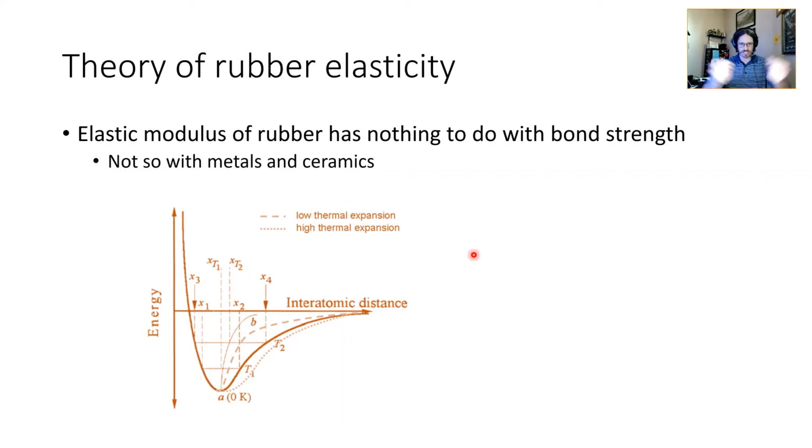It's just those chains elongating that facilitate the stretching of the rubber band, basically. And they have light cross links as compared to a thermoset, so a little bit different behavior. Again, theory of rubber elasticity, it's an entropy driven process. This has some, well, it doesn't really snap back. This would be more viscoelastic, and we'll talk about viscoelasticity a little bit later.